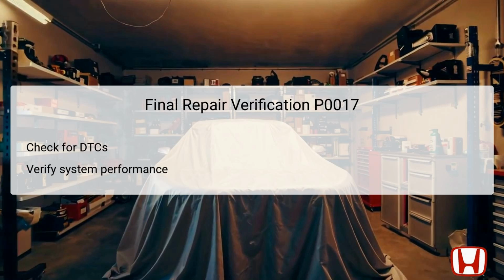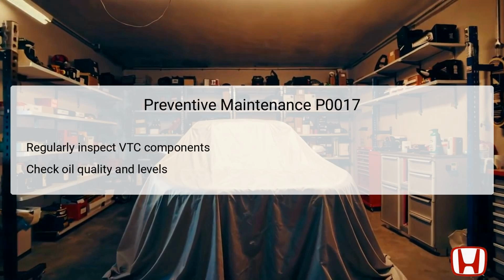To prevent the occurrence of DTC P0017 and ensure the longevity of your Honda Civic's engine, engaging in proactive maintenance is essential. Regular inspections of the VTC components, including the solenoid valves and actuators, should be conducted during service intervals. This helps to identify potential wear or failures before they lead to more severe issues.